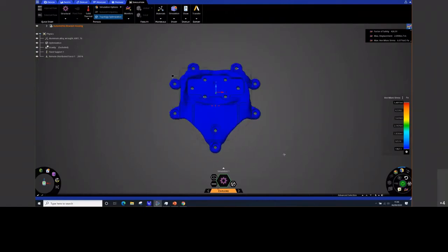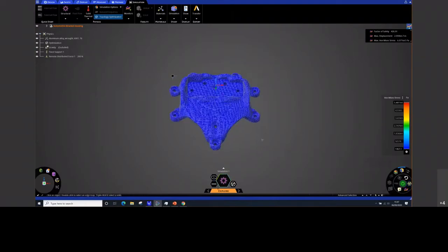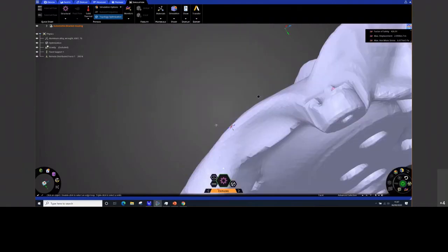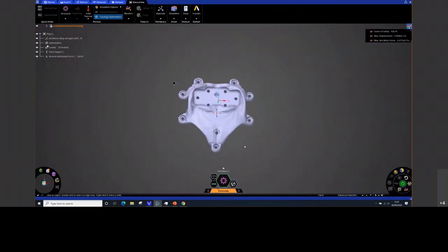And obviously, it's still analysing the model. I'm actually going to then add my optimised body to the model. What that'll do is convert this result into an STL. So literally just by clicking this button, we'll get our result. I'm just going to turn off the actual contour so we can see we've now got an STL body of our optimised shape.